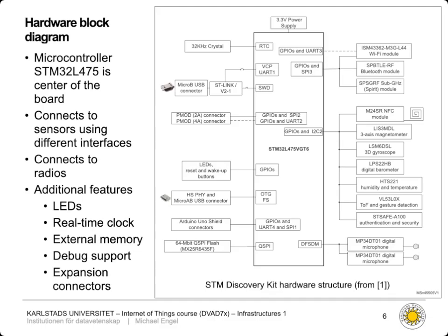So SWD stands for Single Wire Debug Protocol. That's a protocol that was invented by ARM several years back in order to make it really easy and standardized to debug applications running on a physical system. So you don't need an emulator or something to debug your programs. You can just put your program on that device and debug it while it's running, including all the sensors and whatever you connect to it. You also have the expansion connectors I mentioned before, so this system is versatile and allows you to add your own hardware if you need something else or something more than what's provided on that board.